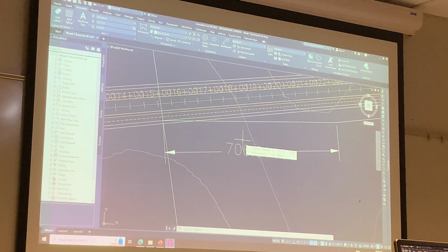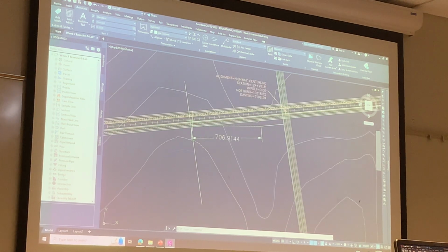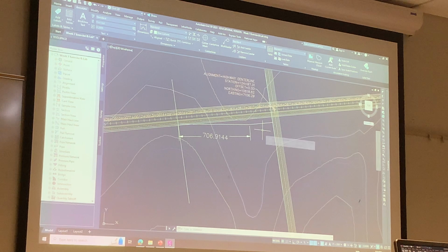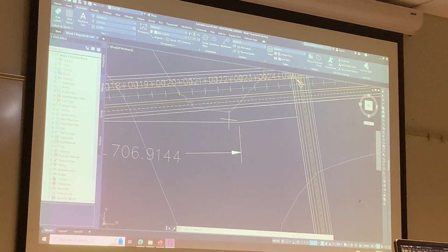So we do kind of like a fraction, right? The change in our speed from one end to the other is 65 to 25, which is 40, so it's changing 40 miles per hour from 0 to 950. So how much is it changing from 0 to 707? That kind of makes sense? Then I just find the change in speed, subtract it from 65, and that gets me whatever my design speed is for this curve.